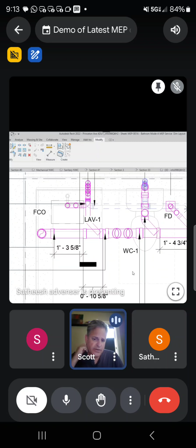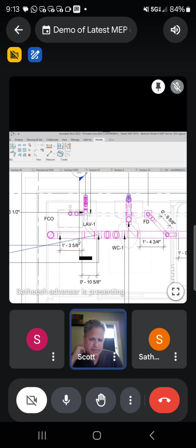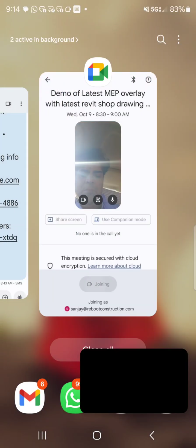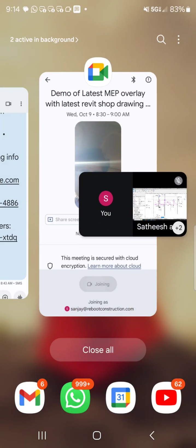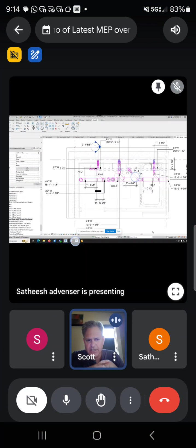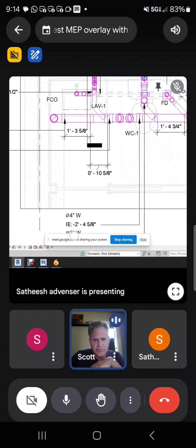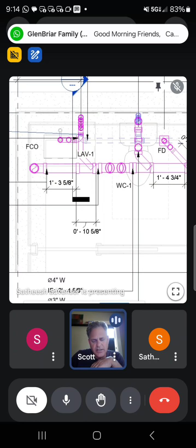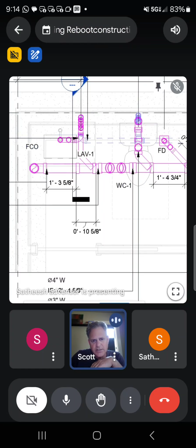What I would like to see is if you zoom out of this drawing a little bit, and you have your walls all grayed out. I love this view. Don't change this view. But for the guys out in the field, I would like to see penetration measurements from a wall, an easy reference that references the architectural drawings, to the center line of the toilets.